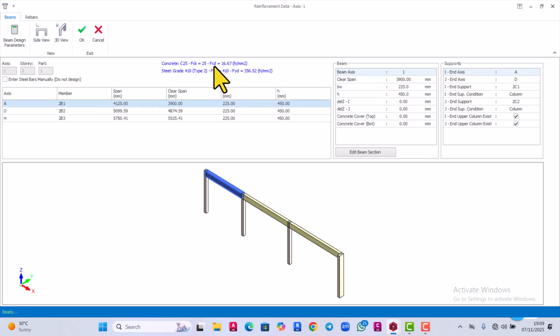Likewise, we specified 410, but Prota is using 356. Even when they use 400, you see that it's still safe. All this needs to account for the errors of site and the material, the way it's being manufactured. Sometimes it's not manufactured up to standard. So that is what this is showing you.